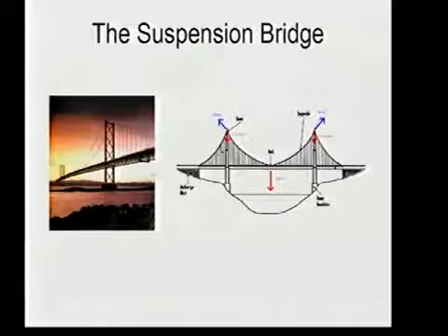The suspension bridge is based on the fact that the end of the bridge's structure out here will not pull in, will pull out, because all of the stresses pulling down come through the cables, and there's a tremendous tension on these ends here. If we go back to the arch bridge, there was tremendous compression holding them in. Suspension bridge, there's tremendous tension.